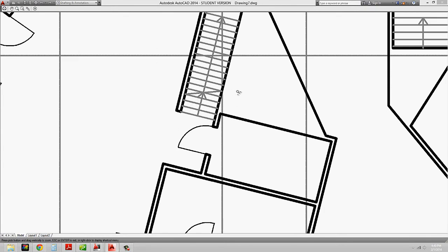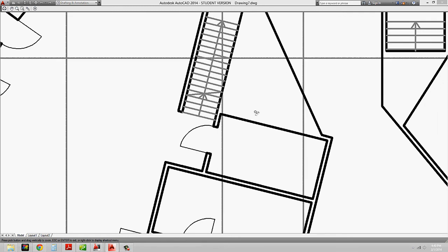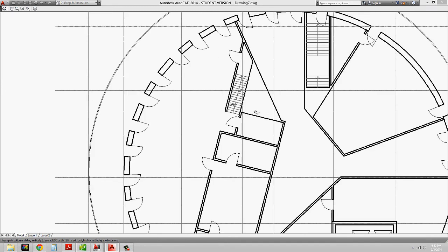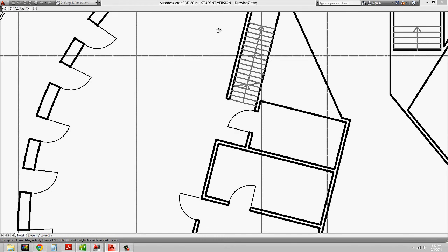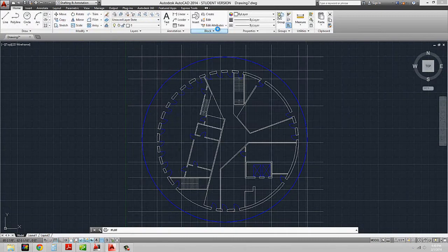And essentially, that's an issue that you're going to have not only with screened lines, because if everything's black, it doesn't really matter what's on top of what. It's all going to get itself sorted out. But when you start to work with screen lines, and if you start to work with colors, as I said, if you don't have a color that's associated with a black pen, and it says use object color, it's going to print out to what that color is. So what you have to look out for is basically the draw order of those objects, okay? And again, it's not like Photoshop where we can just change where it is in the layer list. Really, AutoCAD just kind of throws objects on top of each other.